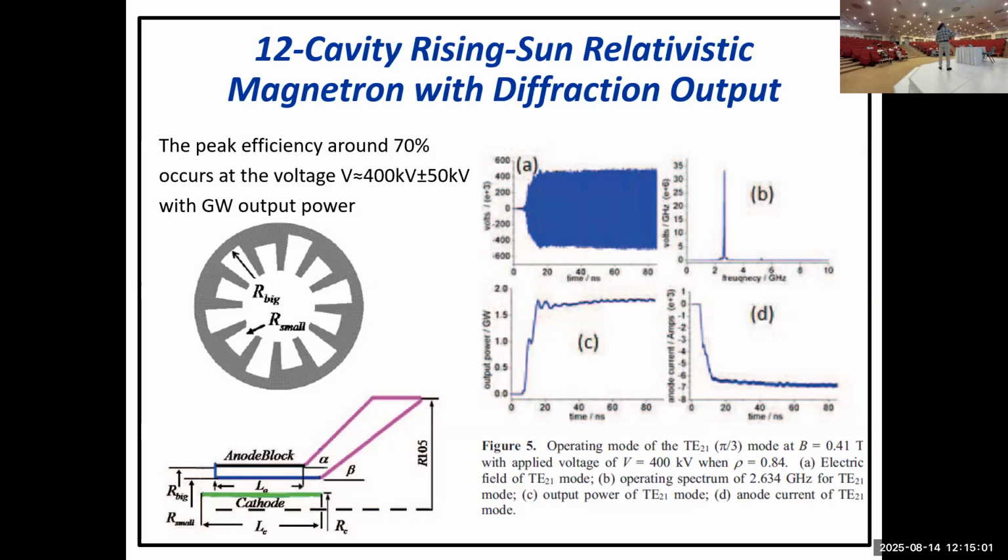Rising sun has 2 cavities, so it's basically averaging over all of these frequencies, right? But there is nothing that says this cannot be done. You can be lucky, run the experiment and get optimal results. Next day, you have a small misalignment, because you have to have the cathode dead on axis, and we do it by hand, there is nothing automated that gives you very nice alignment.